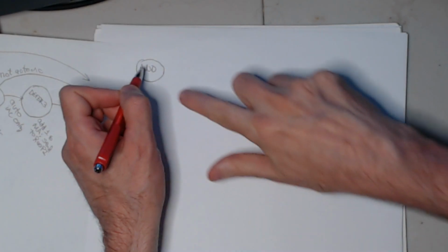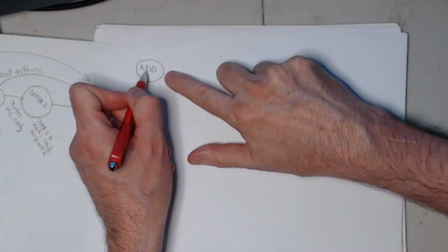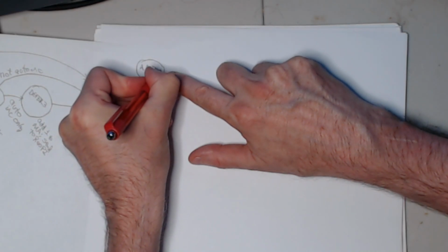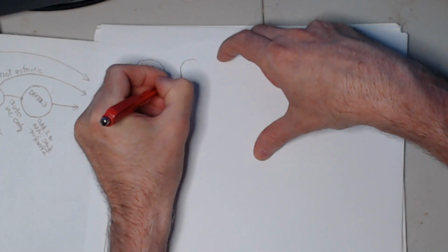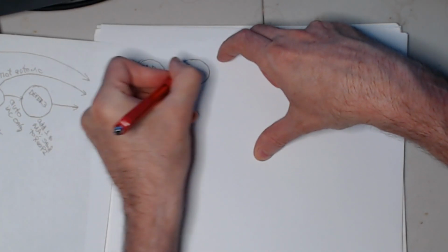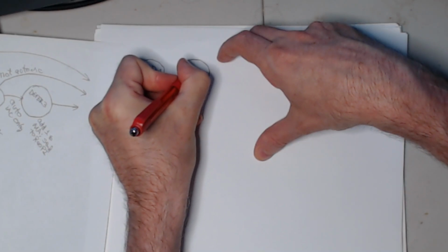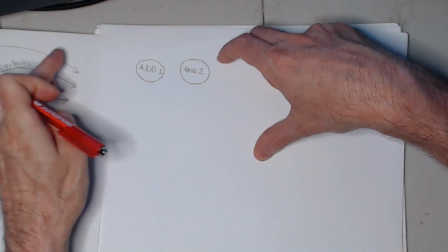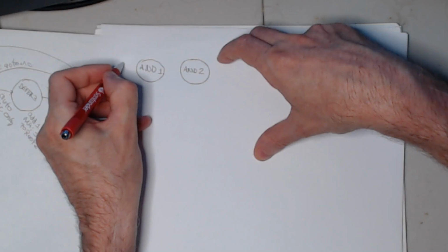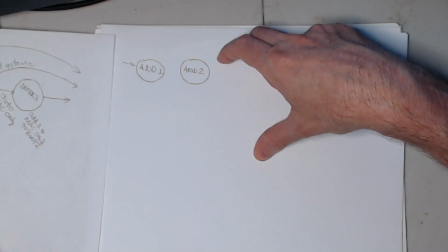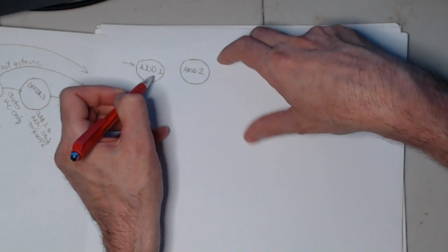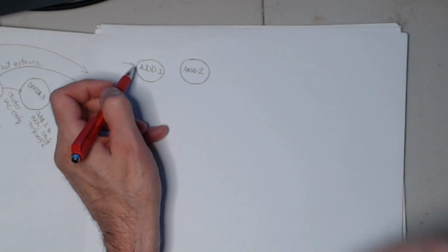So we can send the address of the operand to the Raspberry Pi in the first cycle and read the operand back and update the accumulator in the second cycle. So AND should only take 2 cycles if we do this right. So this comes in here from either fetch or defer 2 or defer 3, could be any one of those. It could come into AND 1 if it's an AND instruction, okay?